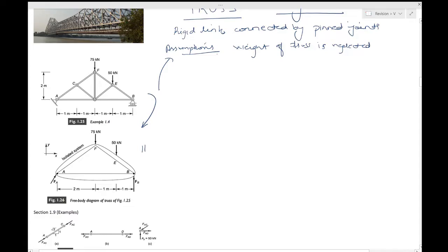Now you trace the periphery of the isolated system. We have included the loads at E and F, so E and F loads you have already taken. At B we have idealized the roller support by showing a vertical reaction FB. Our rationalization, the reason for doing this, the reason this can be done as just a vertical force, is